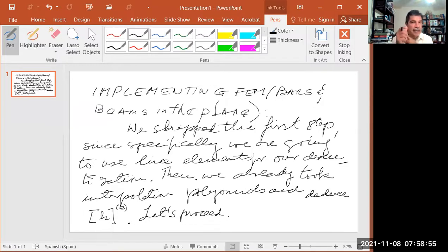So remember, now we have to form the global matrix. Then we have to calculate and implement external forces concentrated, because this is discretization. And also, there are certain geometric boundary conditions that we need to implement in order to take the singularity of the problem out.